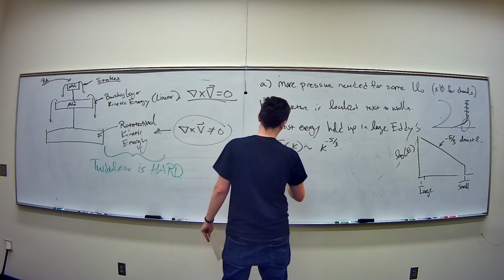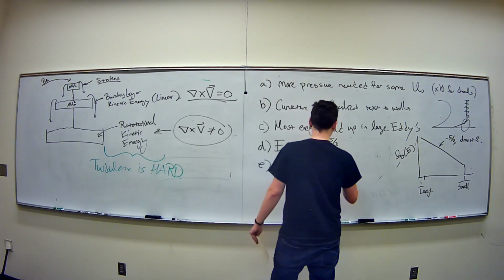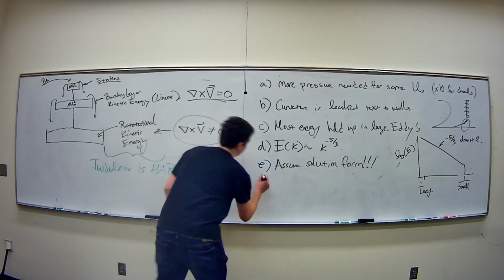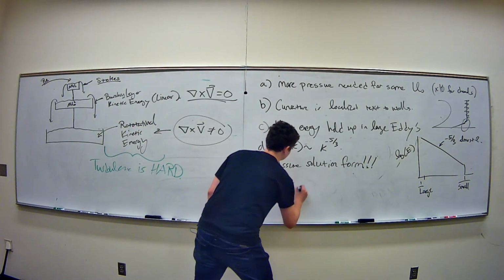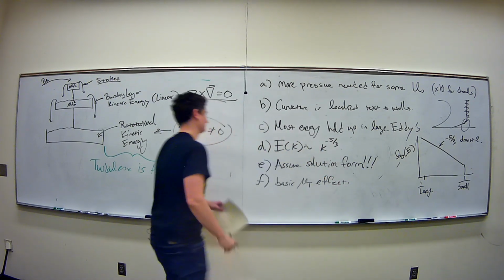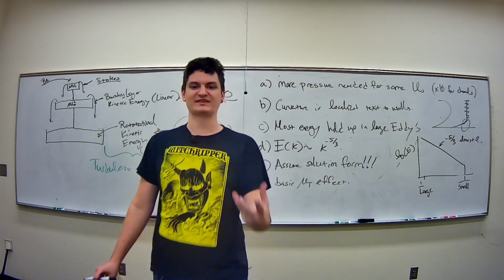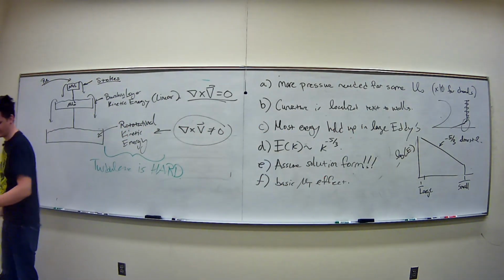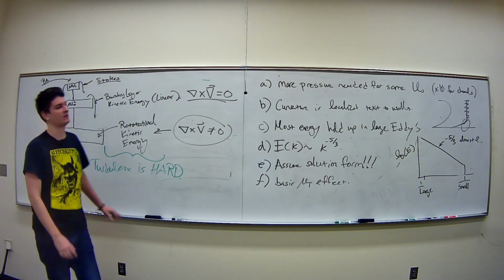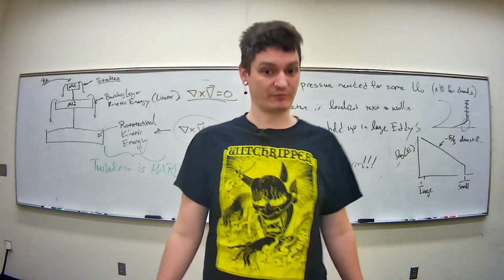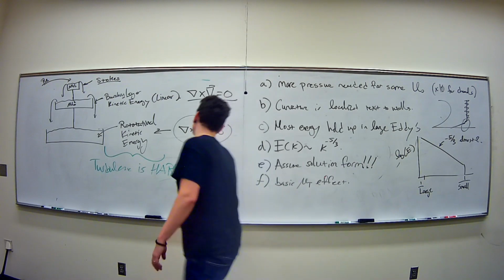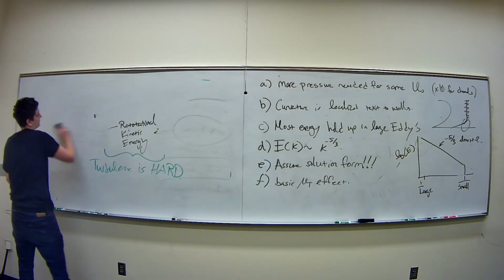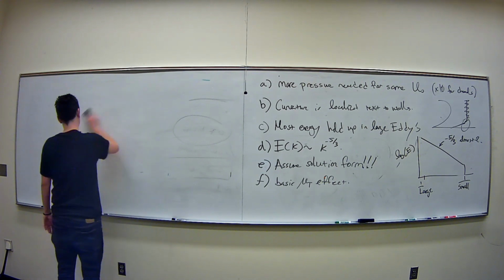Okay, the other thing is, another big thing is we're assuming. Turbulence arises as really an extra viscosity term, and that's that mu t argument that we have. What else do we have? Then I had G and F there. Really you're saying sort of the same thing, and that is that you always are tied to some amount of experiment, whether it's numerical or real experiment. It certainly has to be really done, though. And that makes sense because turbulence is bound to always do experiments, and it's bound to do that because you have to characterize that fluctuation term, or the Reynolds stress, in some way.